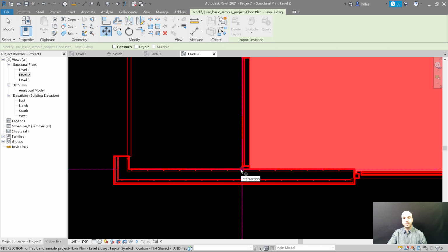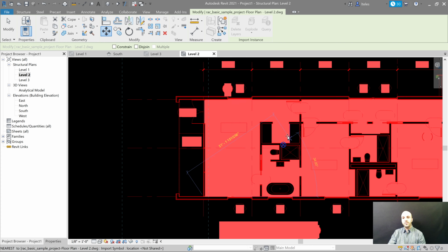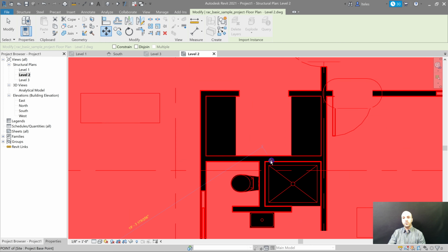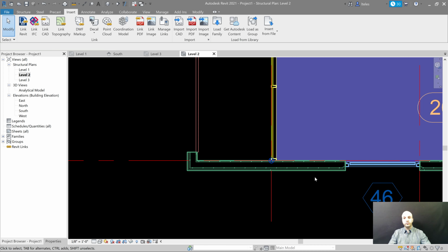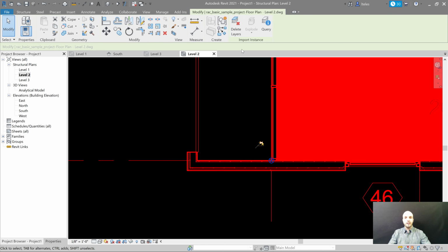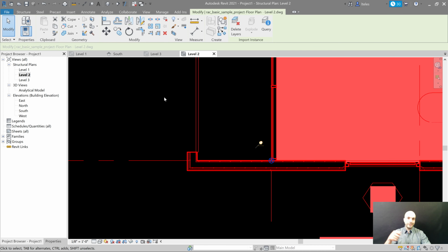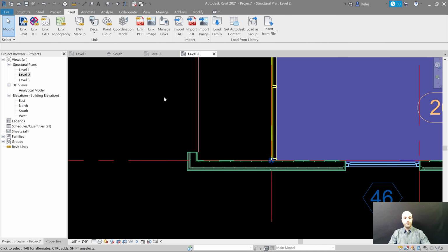It's there. Come on. Right there. That is the intersection of my grids. So I'm going to click to start my location and find the point. Just hover over it until Revit tells me point. Yes, I need this point. After you've moved it, don't forget to go ahead and repin it. Place that thumbtack back on that post-it note.